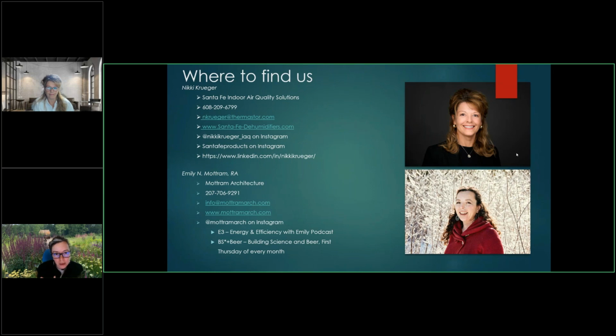Most people don't need HEPA filters in their houses, but there could be an instance or scenario, again, back to that conversation. Exactly. Nikki, this one is specifically for you. Ashley asked for clarification: using a vented dehumidifier would be ill-advised if the home is too tight. What would you say it would need to be if it was below 1 ACH? Otherwise, do we need a balanced system?